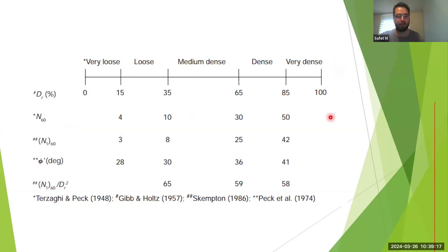So you have a little bit of a table that you can just use to divide your soil. So very loose soil would be everything up to 4 blows per 30 centimeters. 10 would be a border between loose and medium dense, and dense and very dense. This is drawn for the non-cohesive ground, such as gravel and sand.